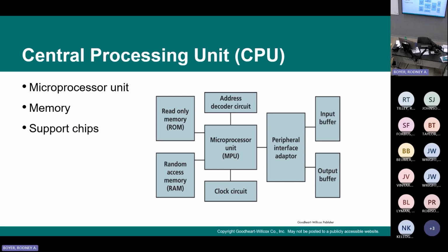Question. When we're comparing processing power of a computer to a regular CPU, like we're talking about, is the comparison more or less that the computer may be able to do more variety, but the CPU, being a much more specific thing, is also a bit more robust? The CPU in your PLC is industrially hardened, which means it's got a bunch of noise shielding and other things on it. But I say it is for a dedicated task. You can't play solitaire on the CPU of a PLC. It just doesn't work.